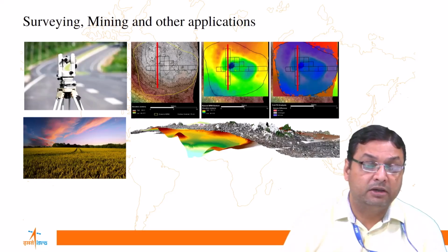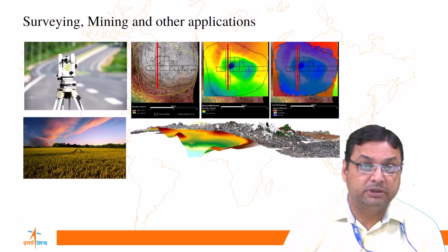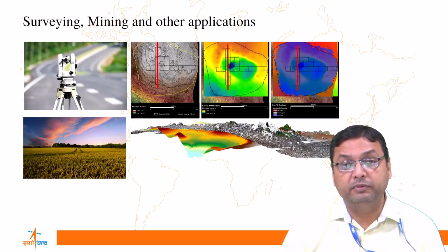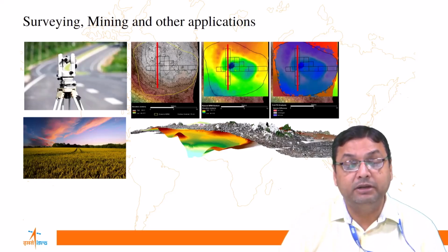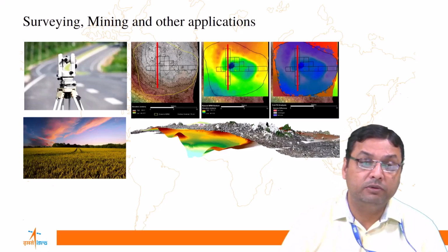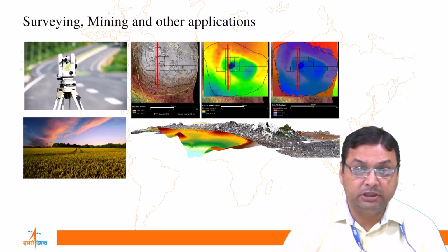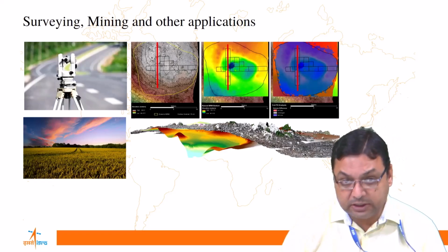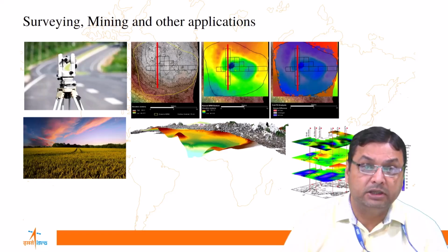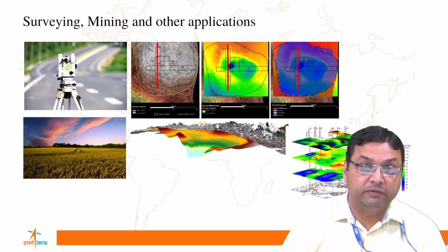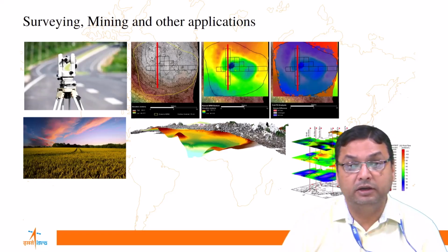GNSS is providing the high accuracy for the planimetric maps, that is the X and Y, and it is also providing the digital elevation models which can be assessed by GPS, and wherein the georeferencing or the satellite triangulation, aerial triangulation has been done by the incorporation of the ground control points which are attained from the GNSS surveys. So these various remote sensing datasets which are highly useful for different types of modelings, they utilize GPS very much, particularly for georeferencing of the datasets in their different layers.